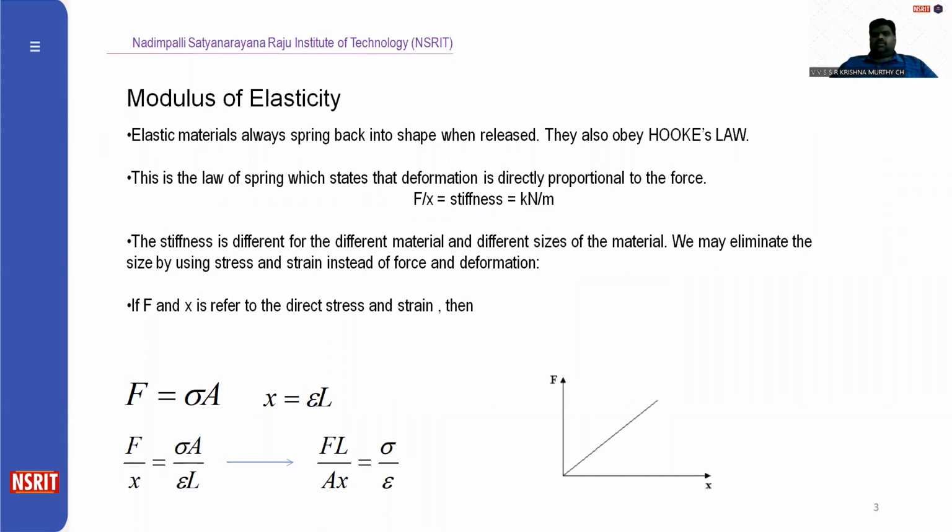Elastic materials always spring back into shape when the load is released. This is also called obeying Hooke's law. So first, let us discuss what we mean by Hooke's law. Hooke's law states that within the elastic limit, the stress is directly proportional to strain. When we consider a spring, the force per unit deformation is nothing but stiffness, and the deformation is directly proportional to the applied force.